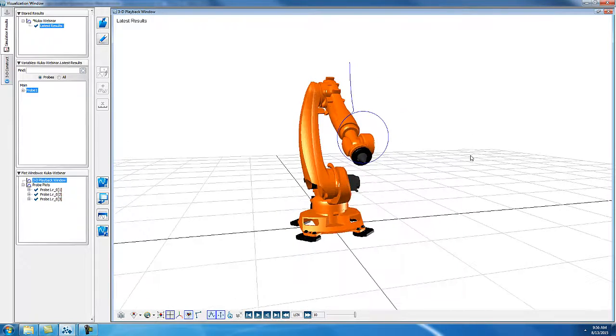One of the benefits of the feedback linearization controller that we used here is that, unlike the PID controllers, there are terms in here that account for the centripetal acceleration needed to stay on that circle. The PID controllers, like I was saying before, they're a linear controller, and so they don't handle these nonlinear constraints perfectly. So what's happening if you use a PID controller instead is that you're actually going to drift outside of this circle, and you're not going to track the circle perfectly. You can add additional terms to PID type controllers to try and compensate for that, but then you're already into a nonlinear control design and you may as well use a more sophisticated technique.